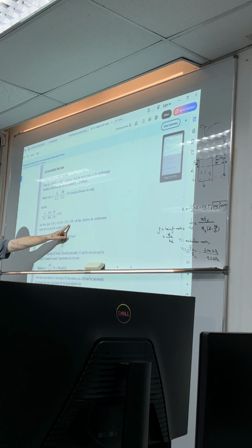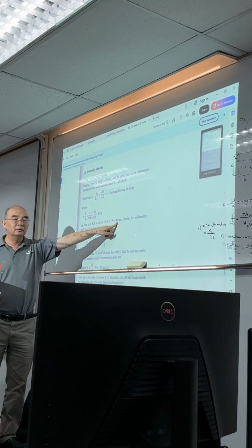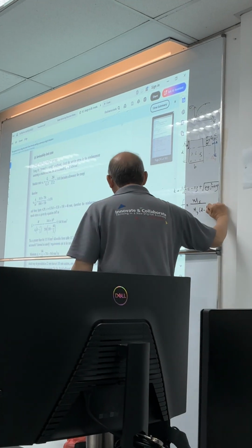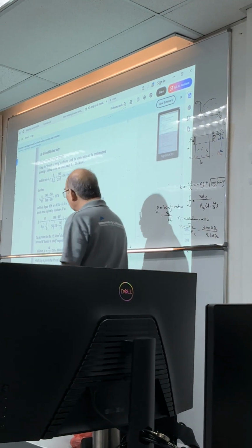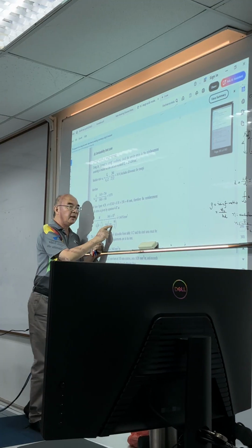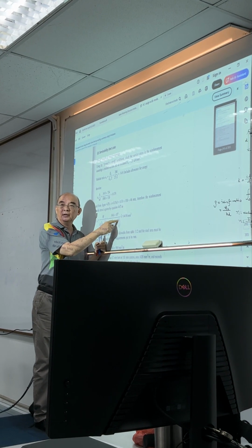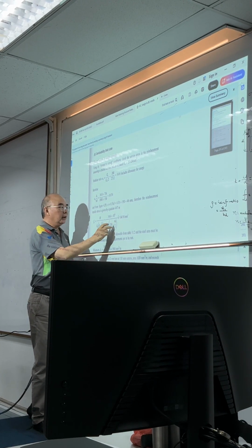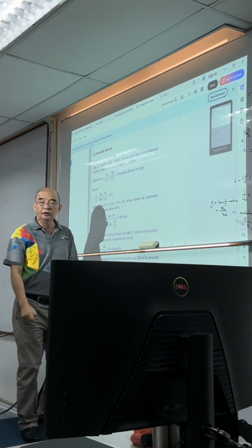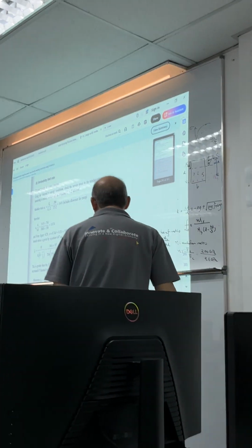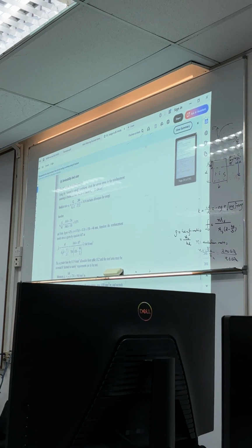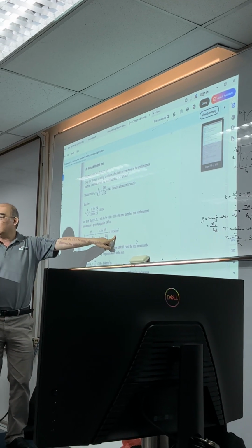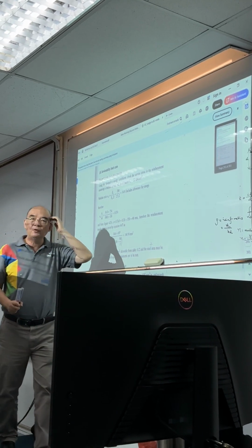So this is K, multiplied by D gives 46 millimeter. So KD is 46 millimeter. This is D minus 1/3 of KD, which gives you the moment arm, and then divided by the area gives you the rebar stress. So the rebar stress is 144 MPa.